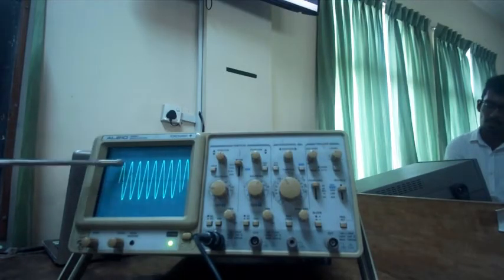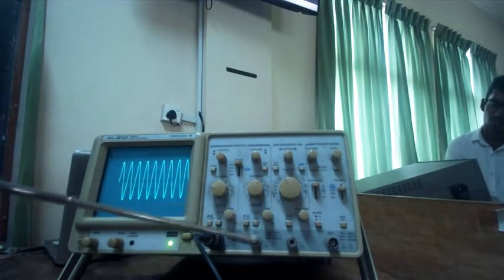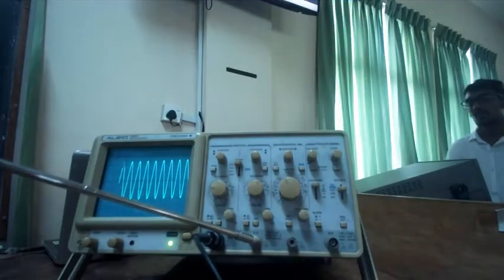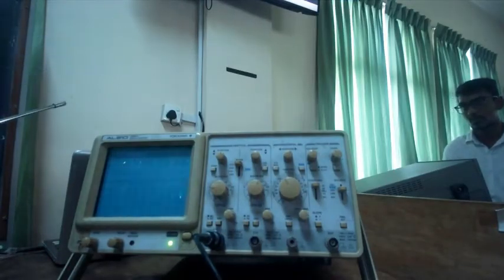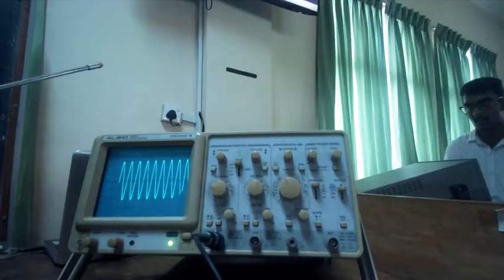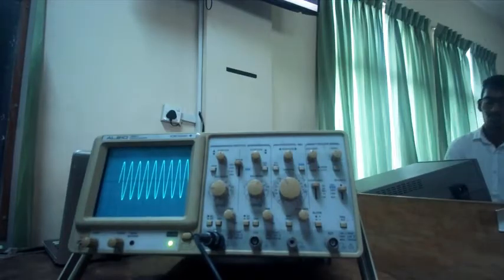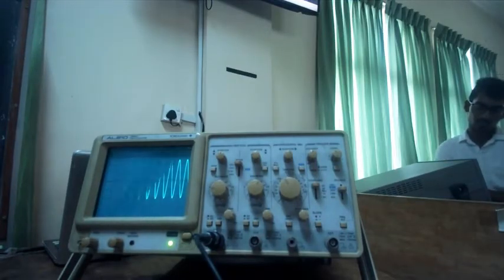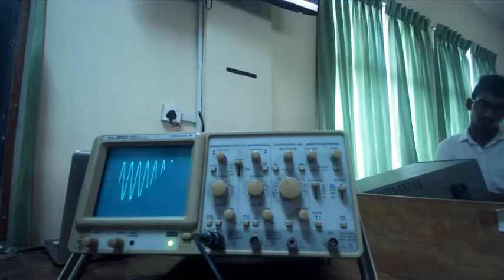So the reason why it triggers now, though there is no signal in channel 2, is because once you sweep, you come back and wait for channel 1 to reach that value. It is not there, but in the next cycle it goes back. You wait until channel 2 reaches, it's not coming. Next cycle it checks channel 1.